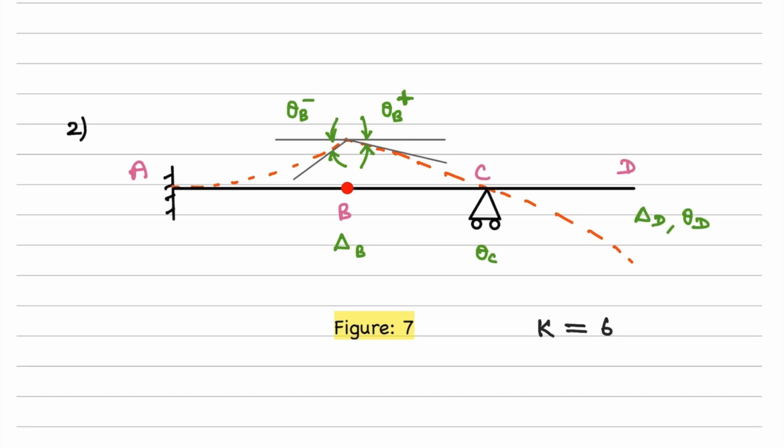We know that when there is a hinge, the moment is 0. That means it is not going to allow moments to be transferred from one span to another, right? What is being 0 here? M is being 0. And what is the corresponding kinematic quantity associated with the moment? It is the rotation. Therefore, at this location, the slope or the rotation will no more be single valued, right?